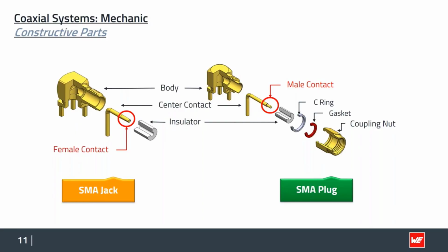On the female side, and this is a point you can watch out for quality, you usually do not use a standard copper alloy stamped contact, but you use copper beryllium contacts or related materials that are more flexible and will not wear out so early, so they can keep the same tension over all the 500 life cycles, or if they are connected for a long time, to provide the same performance in electrical resistance and all the technical data, so that your signal transmission is stable.